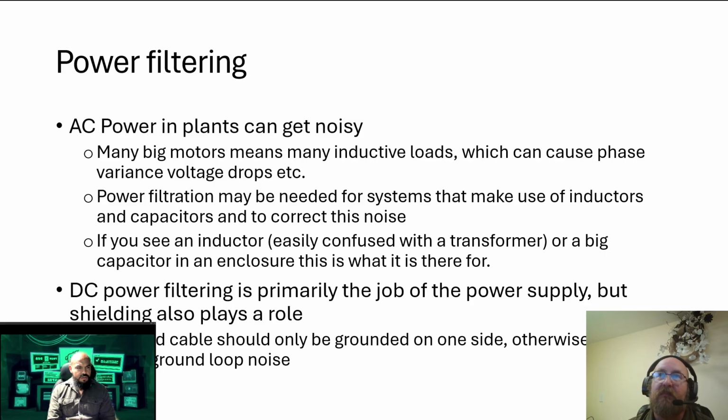So many different industries require filtration of some kind. Depending on what you're using, certain sensitive pieces of equipment will definitely need to be taken into account. Especially anytime you're working with an AC servo motor, getting that noise-free AC going into an AC servo is important. You're going to want to have a filter on that system in order to make sure that it is following your commands correctly, because you want precision motion control out of that application. You don't want the noise all of a sudden making that motion control a little iffy. It'll be unusable at that point, depending on what you're using it for.